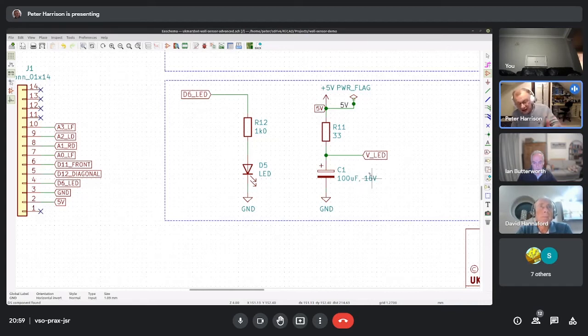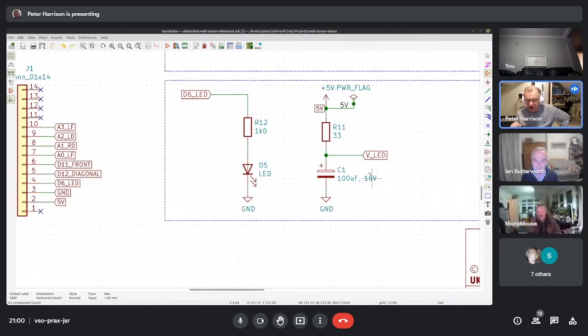All these various steps are not things that you have to do in Eagle, and the reason for talking about them tonight is to point out that it is different, and it may seem like a bit of a chore to have to do these various things when in Eagle you just click on board and away you go. But we have also all come across the big disadvantage to that in Eagle, which is that if anything goes wrong, it just says schematic and board are no longer in sync. You're dead. Now what do you want to do?